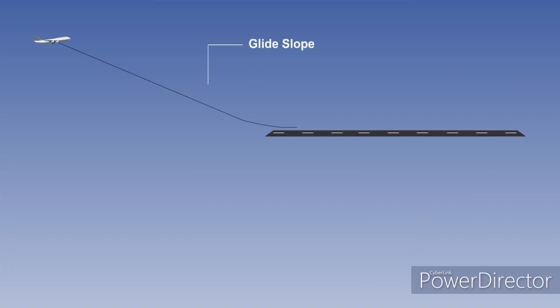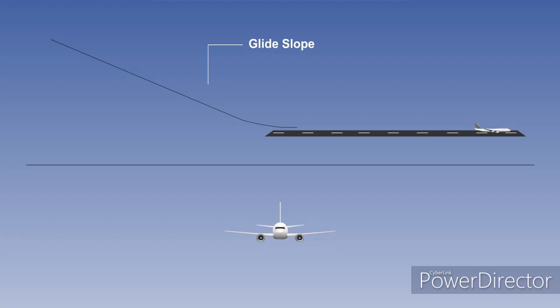Mode 6B adds two further safety features to the GPWS system and consists of height callouts on approach and bank angle alert. 500. 100. 50. 40. 30. 10. Bank angle is to warn crews of excessive roll rates. The bank angle limit reduces the closer to the ground the aeroplane is because of reduced wingtip and engine pod clearance.